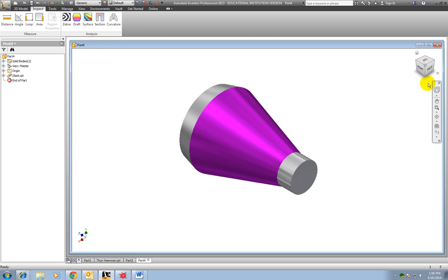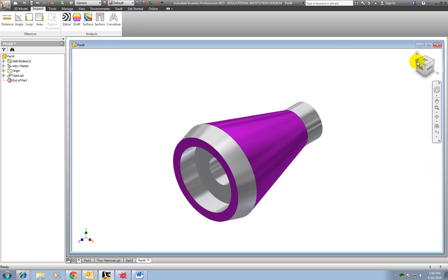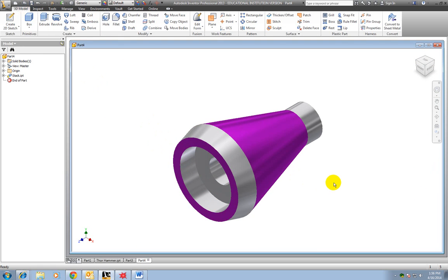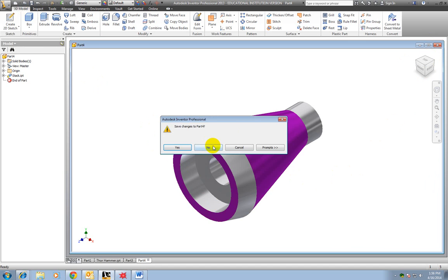So you can do this in two different ways, though Derive really isn't considered parametric. Parametric equations is when you actually write out those equations and just change one number. Derive is if you already have the part made and you want to scale it to a different size.